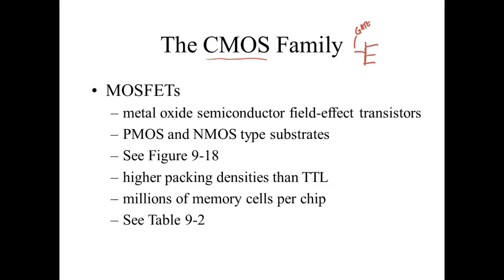And all you need to do, these guys are less than $10, you just put them on your arm. And then, well, you have a static mat that you set stuff on. You clip this onto your mat, and everybody gets at the same potential, and you can't hurt it. It's called a static wristband. You see guys that are really, really susceptible to static discharge. They'll have a static thing around their ankle when they're wearing tennis shoes, and it's just a pad down there that discharges them.